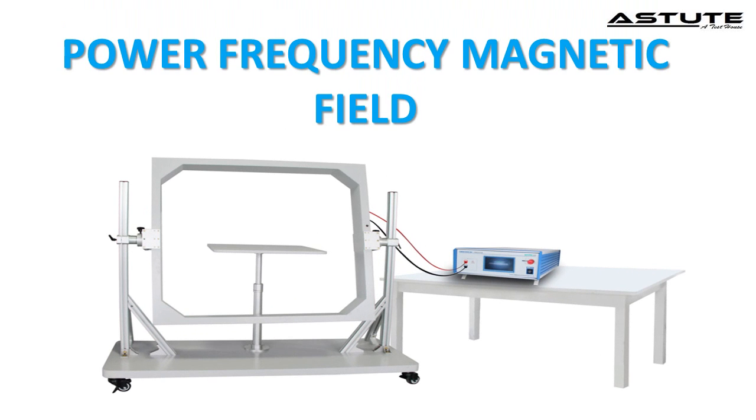The magnetic fields to which equipment is subjected may influence the reliable operation of equipment and systems. These tests are intended to demonstrate the immunity of equipment when subjected to power frequency magnetic fields related to the specific locations and installation conditions of the equipment. The power frequency magnetic field is generated by power frequency current in conductors or, more seldom, from other devices in the proximity of equipment.